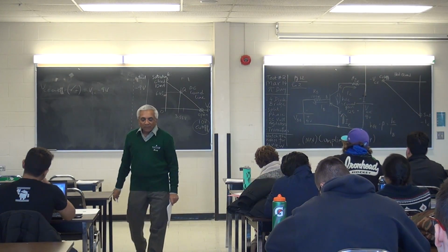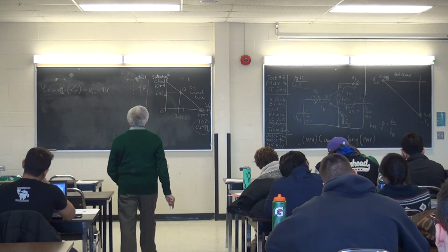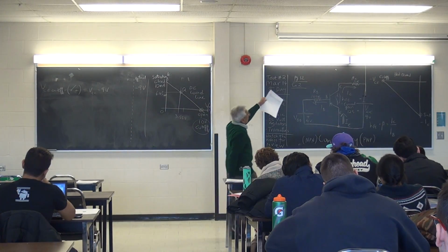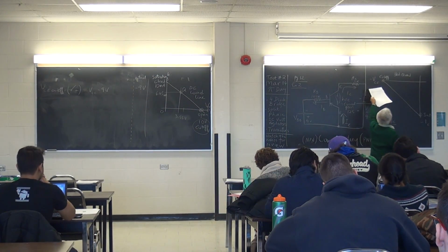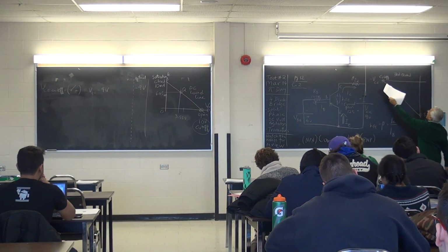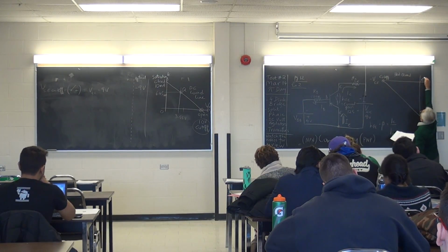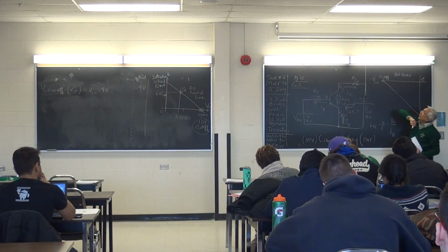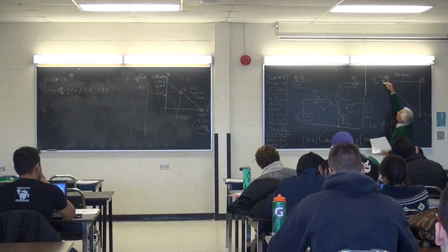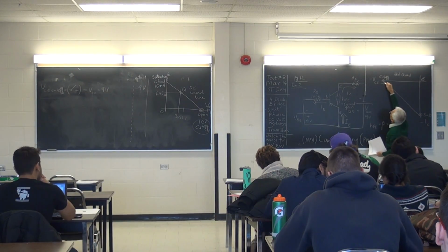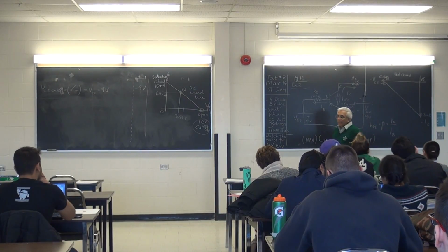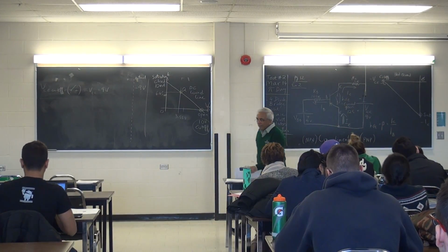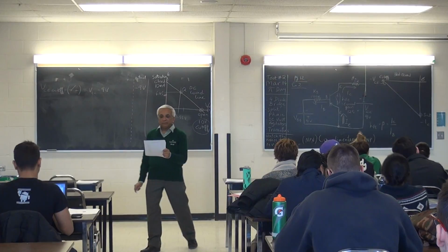So VCE cutoff is negative 9 volts, and what I'm going to show then is the negative 9 volts on my graph. Put a 0 to identify where the two axes intersect and indicate negative 9 volts here. So that's my cutoff point. That's where the transistor acts like an open switch.